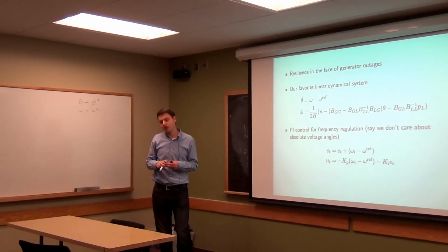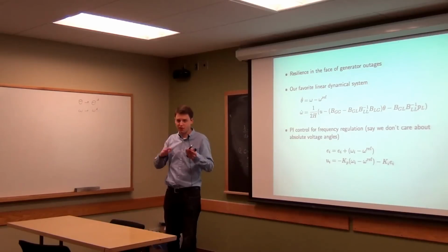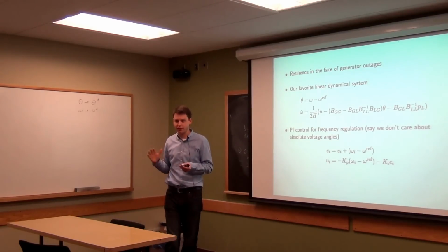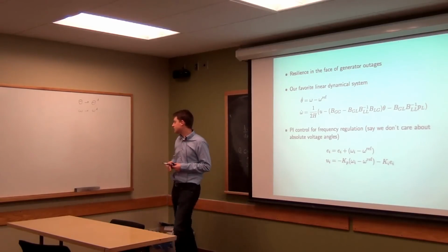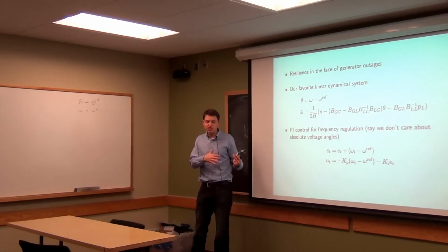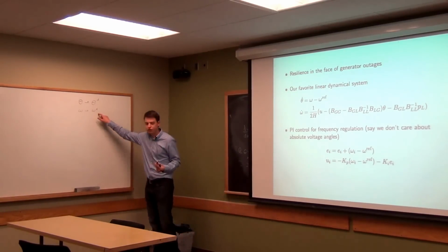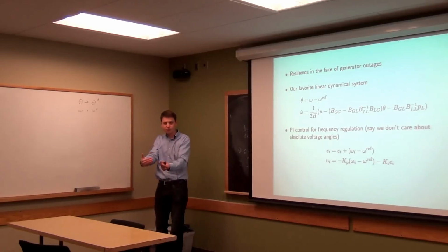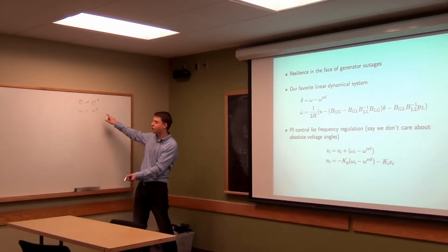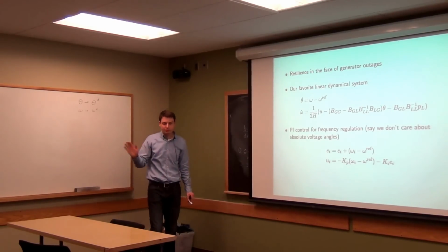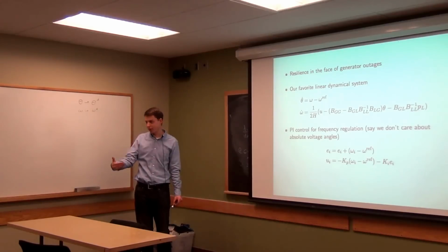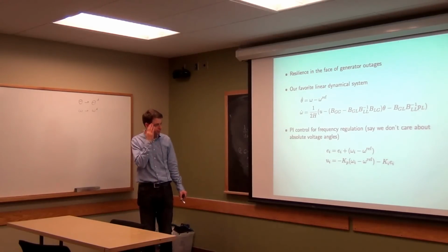And as long as generators can produce more or less power, depending on where they happen to be in the network, and they have some flexibility there, that works okay. As I said before, in the real situation, you might have some generators that do this, and other ones just produce a fixed amount of power, and then some others that regulate frequency. But we'll assume that for now they're all working to regulate frequency.